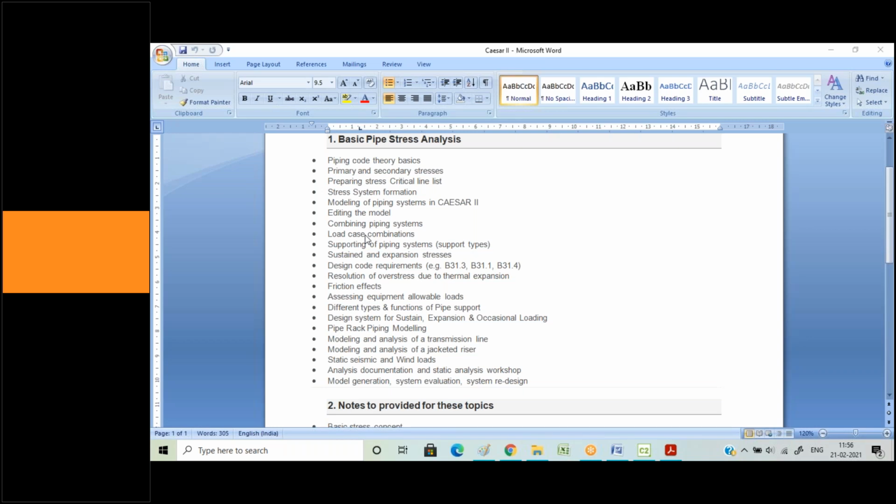Now when you come to this particular location and you have to place a spring, the stress engineer recommends the hot load, the cold load, the spring constant, whatever number of things he's recommending to you. He's prepared a data sheet, you have sent it to your vendor, the vendor has sent you the required spring with the required spring constant, and you have placed it below the line. The line is not in operating condition, it is not being commissioned.